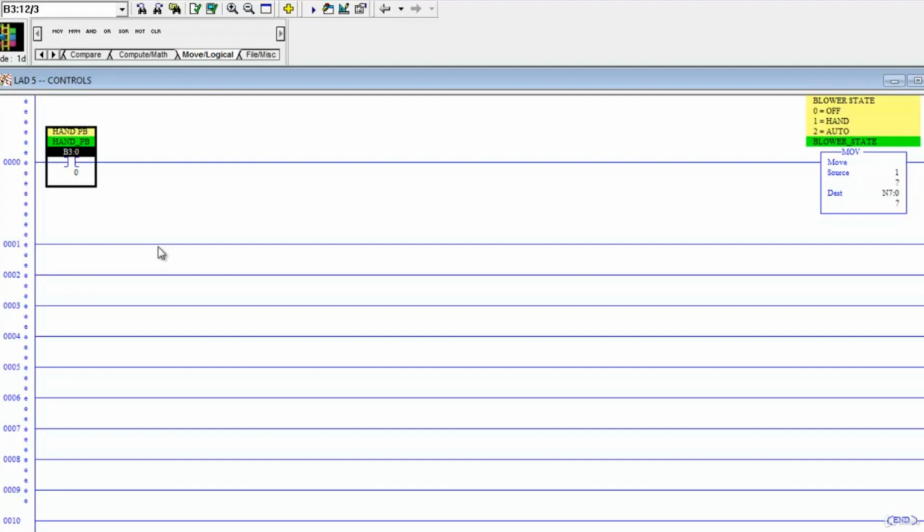And when we want a push button to trigger one single instantaneous action, we need to program our control logic so that a single button push doesn't cause the same action to happen 20 or 30 times. And the one shot is the instruction that allows us to do that.